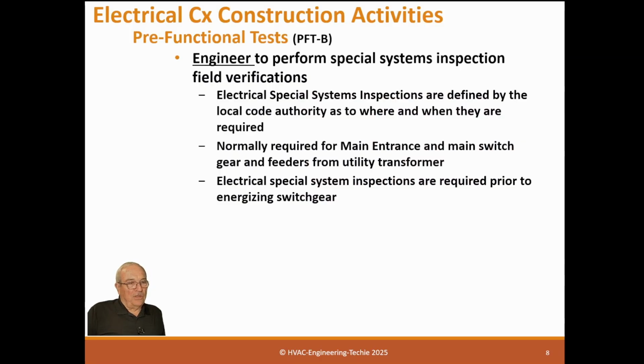What happened, there was a large hotel that started up before me, and an electrician had inadvertently left a wrench across the main bus bars. And when they energized it, it vaporized the bus bar and took out the substation. So that utility lost the substation because of this problem. And it was because it was high voltage, a medium voltage according to the utility, but still.